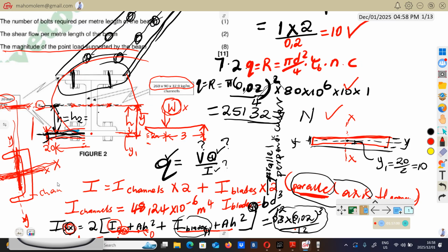Since I've started with y bar, to find this y bar you just have to find the height of everything, starting from here to there, and divide by 2. That will be the center of everything, of this thing combined. So to find this total height, you will say this one is 20, from here to there, plus this height.